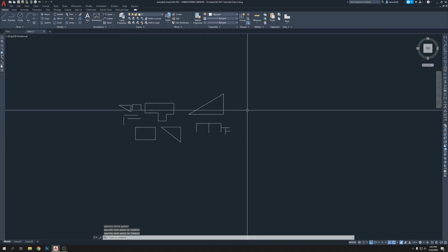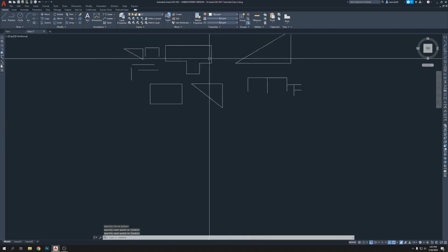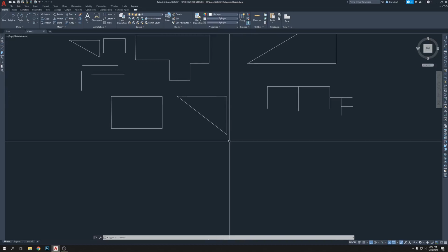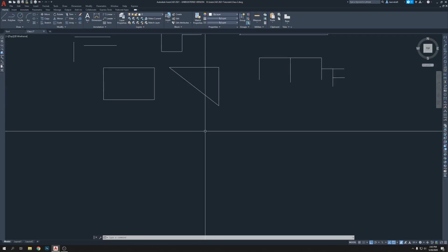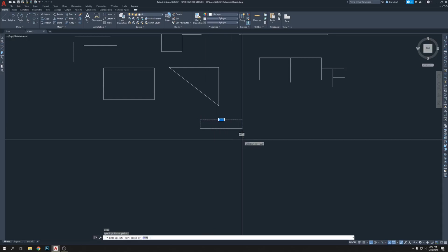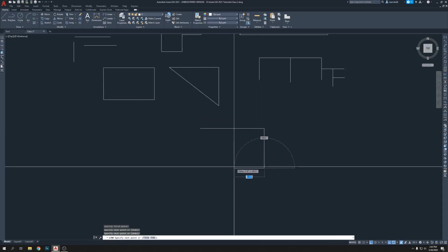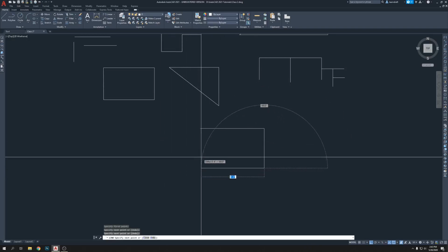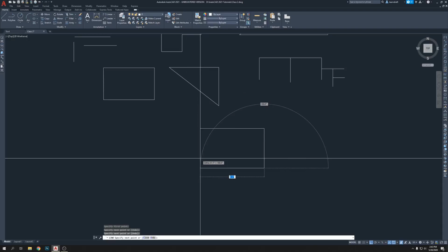See, this is how. So let's keep it here, and we're gonna draw a box with the line. So L, enter, click, click, click, and you can go anywhere. See this cursor size, if it is full, like 100%, then you can just align.